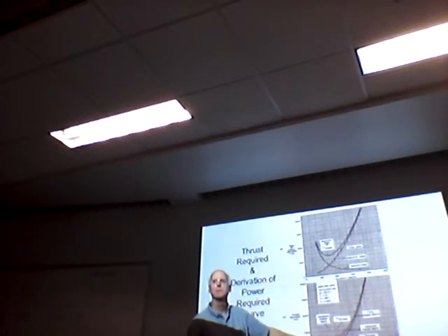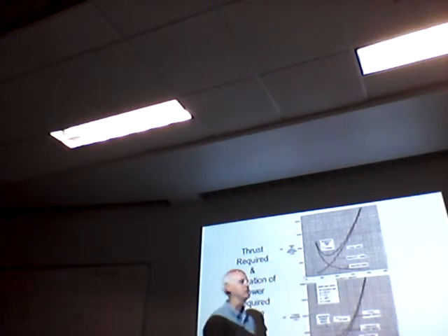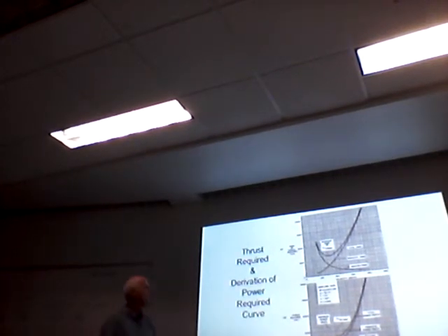Is that what it does? It really just compensates for the lag that you have with the jet? Yeah, part of that is exactly that. And the fact that in a jet engine, from idle to 80%, it's hardly any change at all. From 80% on up, then you've got a lot of change. So the way that the engine responds has a lot to do with that. But you ought to be able to recognize the difference between the two.